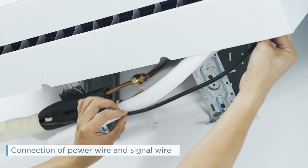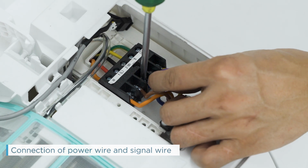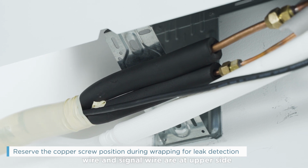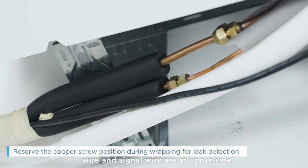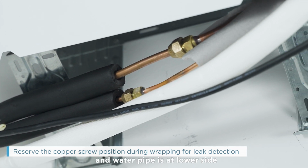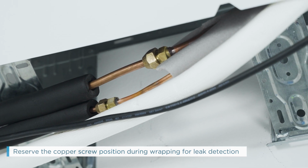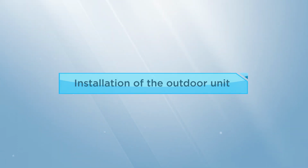Connection of power wire and signal wire. Wrapping is conducted in order where power wire and signal wire are at the upper side, connecting pipe is in the middle, and water pipe is at the lower side. Reserve the copper screw position during wrapping for leak detection. Installation of the outdoor unit.